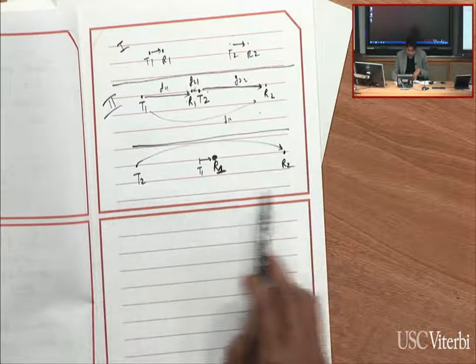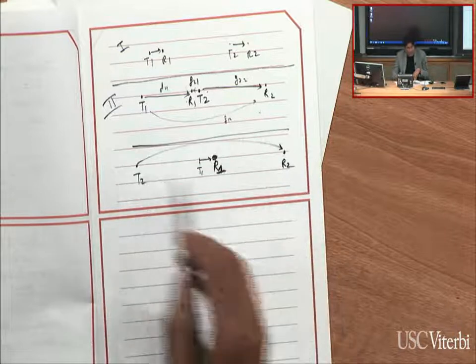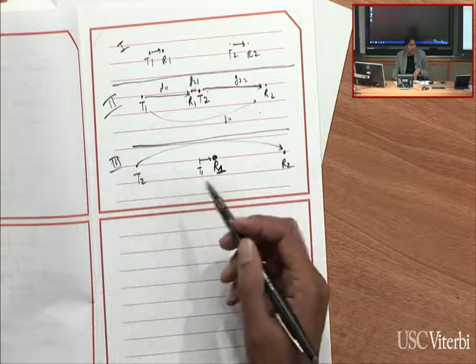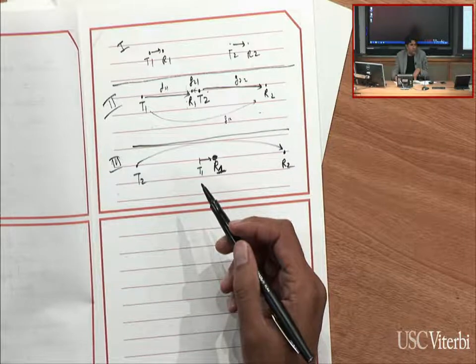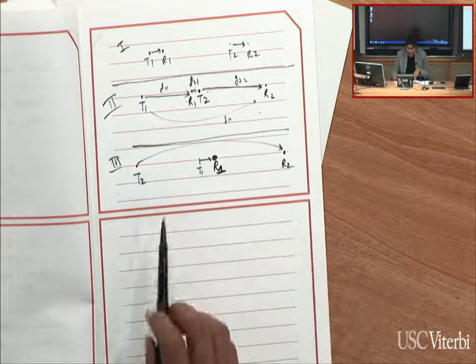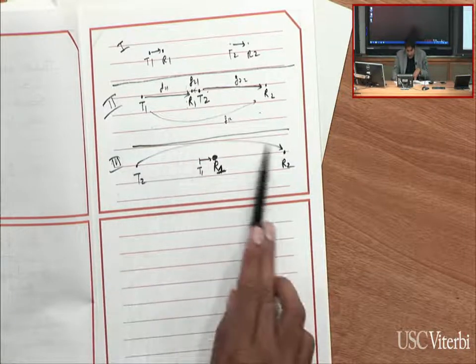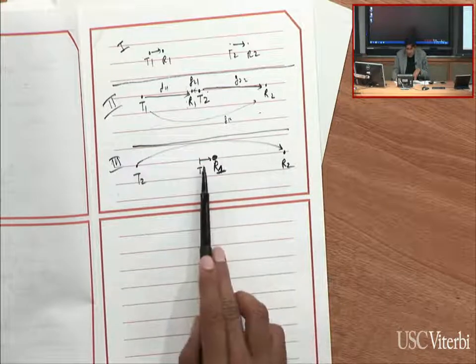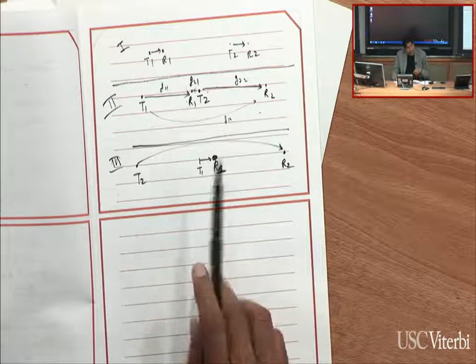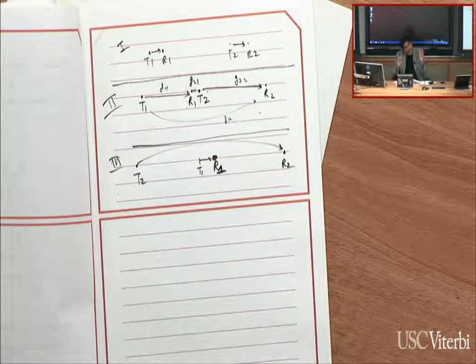But it turns out that for this type of scenario, surprisingly, it's actually not very hard in many cases to find a power control solution. And the intuition is that even though this gain is weak, this gain is really large. So it's like in that first part, G11 is kind of compensating for G22 being kind of weak.